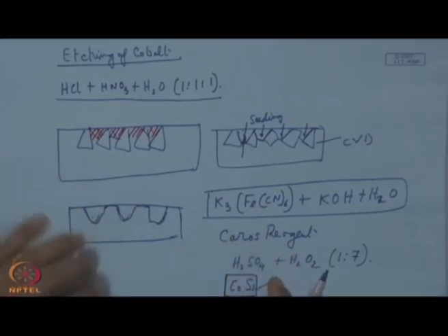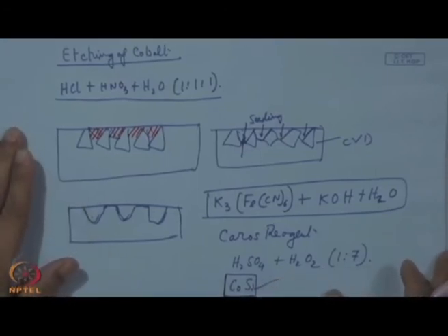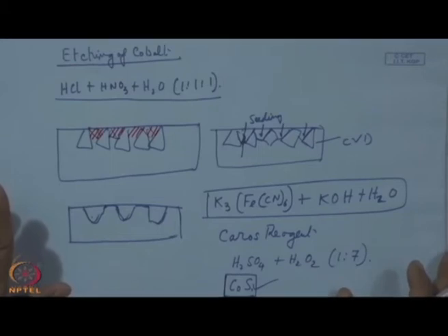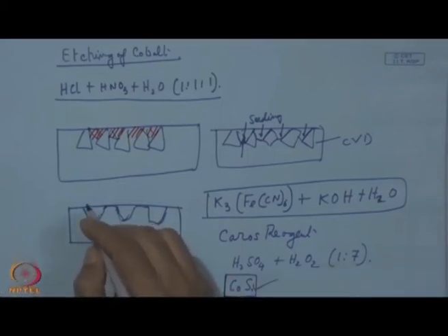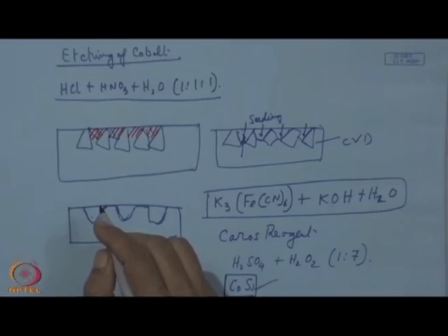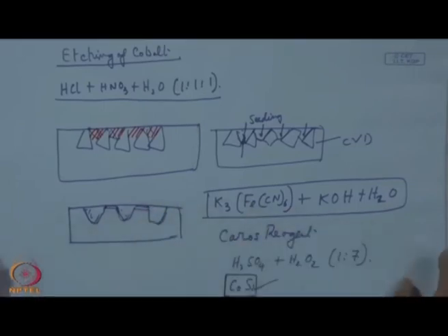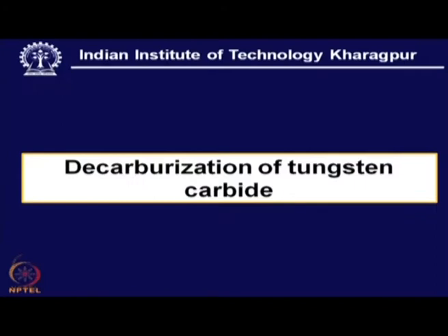So, this is another way of handling the thing, and as we have already seen, it is a substrate preparation step which is unlike that of other CVD coating processes, as for example CVD of TiC or TiN or aluminum oxide. There we do not require that special treatment or special attention so far as the substrate chemistry is concerned. So, now here what we see is actually seeding, and this seeding is done in this pocket with total passivation of this layer. There are various processes which have been successfully attempted, and this is one of those.